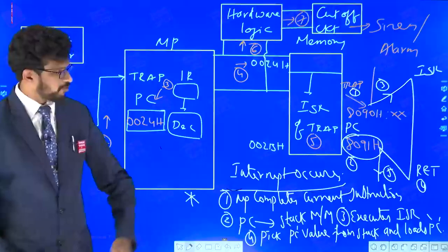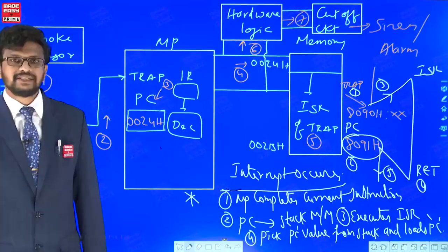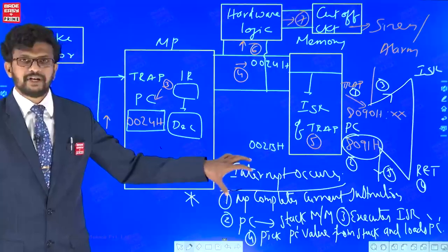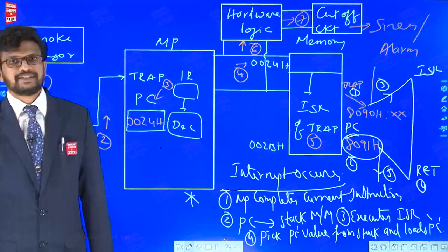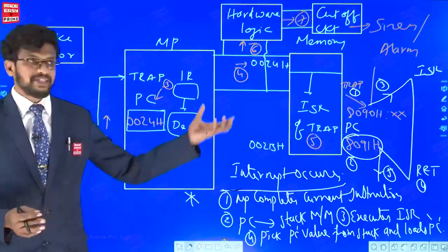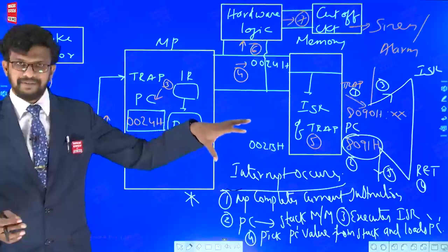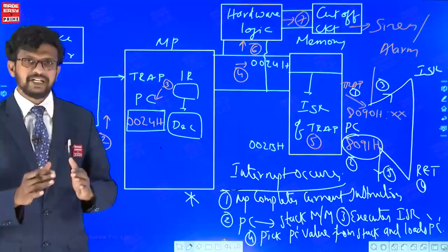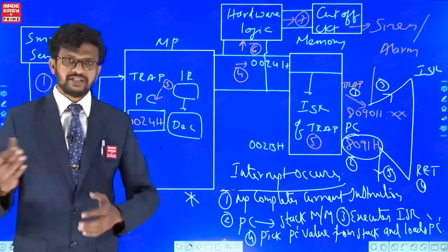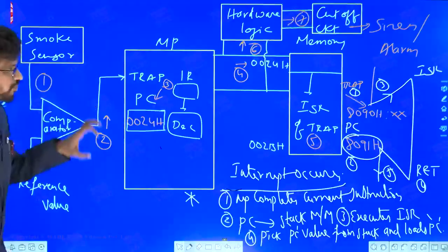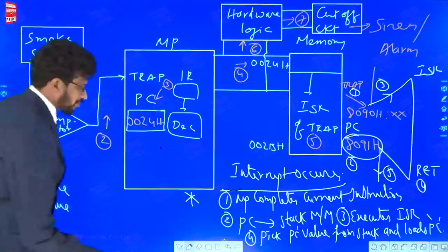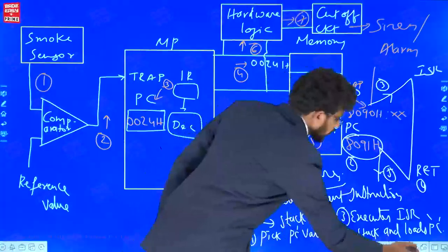There are several types of questions possible from this sequence of interrupt. The same concept can also be understood for the call instruction. The call instruction is the same as an interrupt, but it is one instruction, whereas interrupts are present on the pin. We shall discuss later how the concept matches in the instruction set architecture. I hope you understood the concept of trap very clearly. Now let us go to the next.